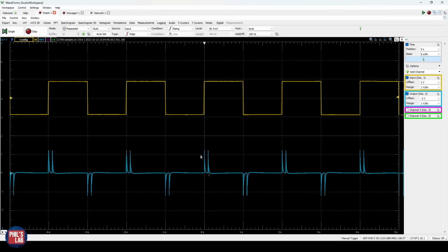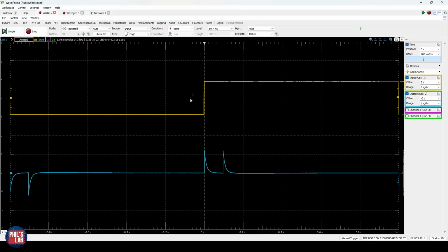The first peak, you can see in the center at 0 seconds, is due to our current input samples times alpha. The second peak is actually due to our delay line times beta, which is about 100 milliseconds after the initial transition. So we have the initial signal on the left, and on the right-hand side we have a delayed signal,